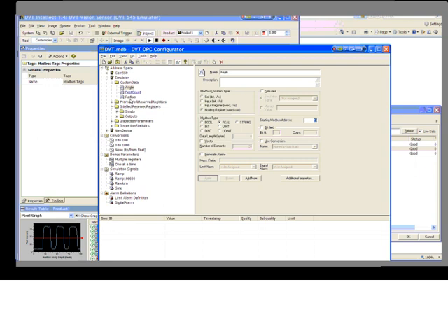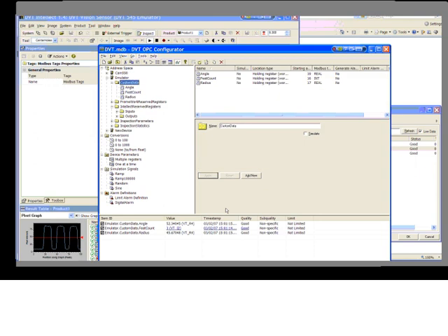Remember, you can use the monitoring view only for monitoring purposes, just to make sure that everything is okay. There's a timestamp on those values, and there's a quality, which refers to several things. For example, the tag was always acquired. There were no problems. There were no packets that got skipped or polling periods where we couldn't get this data.